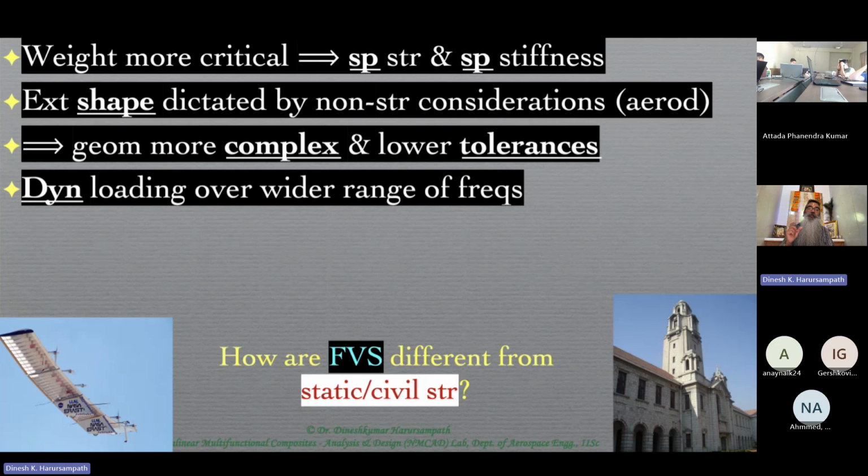These terms, margin of safety, factor, we'll define a little more precisely as we go forward, but you can understand that for now in a qualitative sense: there is a particular critical load that we expect this building to take under certain maximum wind speeds that it might encounter in a particular season throughout the year, based on historical data and extrapolating it for the future. And then typically also the seismic conditions in those locations.